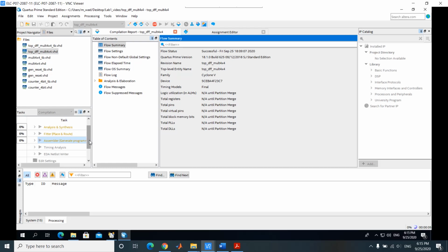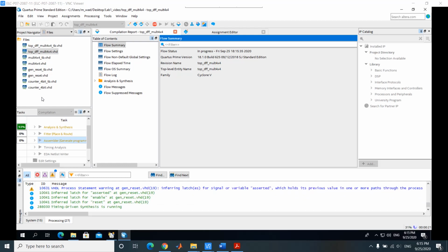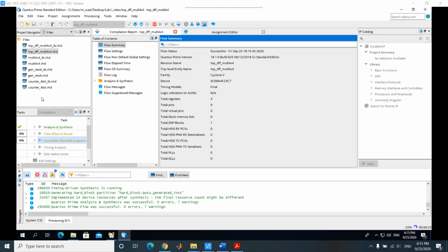We made the pin assignment step, and now we will create our clock as specified in the manual. For creating the clock, we need to add another file called a .sdc file. It is called Synopsys Design Constraint, and SDC is the shortening of the name.